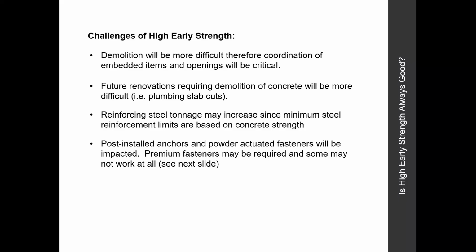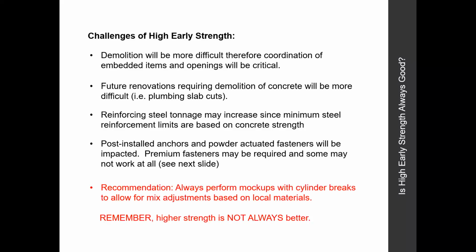Post-installed anchors and powder-actuated fasteners may be impacted. Recommendation: always perform mockups. Local materials are going to vary. It's going to be different. You need to take cylinder breaks with that mockup and require that in your specifications. And remember that higher strength is not always necessarily better. There are some challenges that could come with that.